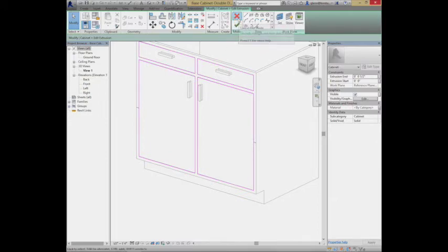To do that, did they put a plane in front of the cabinet? Exactly. They put a reference plane right on the cabinet face, and that reference plane is doing 2 things. It's controlling the depth of the cabinet, but it's also the plane on which we're drawing the extrusions. So reference planes are really the key to all this. Think about everything in terms of planes. In fact, let's show you those in just a second.